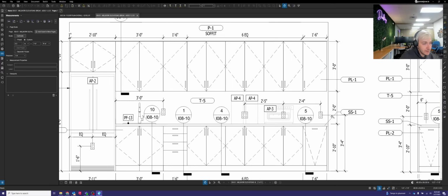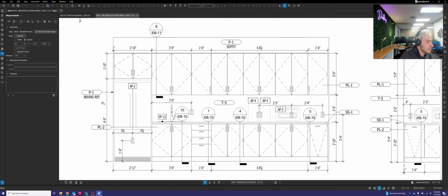Also, taking a look at some of the materials involved with this drawing. It looks like this P1 will most likely be paint 1, or wall paint. We can look at the finish schedule in the job and confirm that, but that'll probably be drywall back there, so we might not actually have anything to do with that. That's on the print from the architect because it affects multiple areas of scope. Although we're mainly focused on just the cabinets and our scope of work, they have to provide information for all the other trades too, including the appliance vendor, the plumber, and the drywallers.